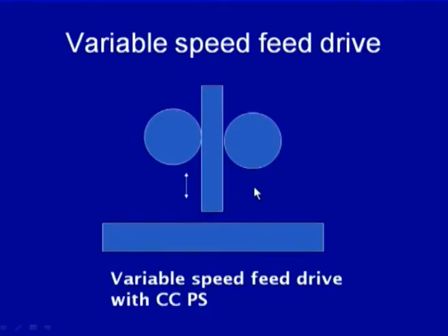So, if the arc gap is increased, this increase in arc gap will be increasing the arc voltage, and this increase in arc voltage is used as input to reduce the current being fed in the motor drive system to drive these rollers, so that the speed of these rollers can be reduced, because the speed of these rollers will be deciding the speed at which the electrode is being fed during the arc welding.